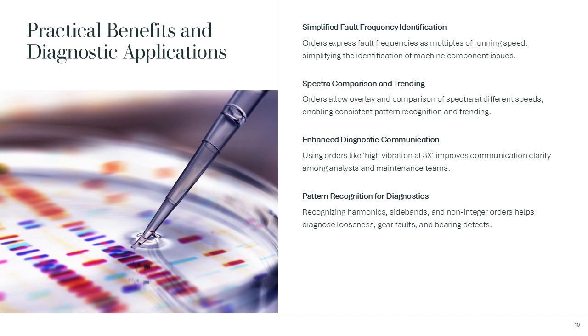In diagnostic applications, recognizing patterns such as harmonics, sidebands, and non-integer orders helps pinpoint issues like looseness, gear faults, and bearing defects. By leveraging orders, analysts can improve accuracy, efficiency, and confidence in their assessments, ultimately enhancing machine reliability and reducing downtime.